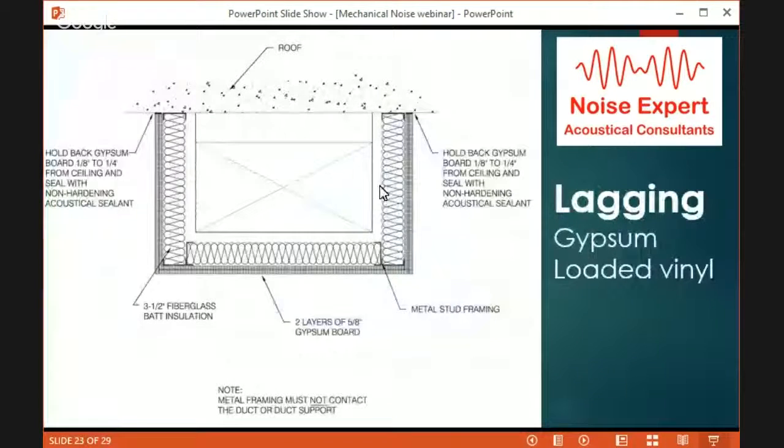I guess that's my only figure. We did this a lot where you're just trying to add stiffening to this. You can attach drywall. We actually used aluminum framing at one point to not add a lot of mass, but we're trying to add stiffening to the duct, like a round duct. Again, just be aware that's pushing the low frequency downstream. But if there's a noise sensitive area you just want to avoid, or you're just trying to treat it until the silencer, you have a place for a silencer, then you can stiffen the duct, and that'll help the noise not break out. This takes a lot of space, so it's not the most practical above a ceiling.